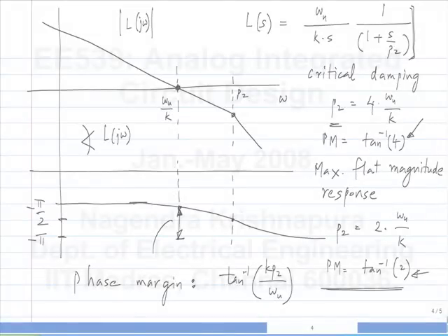Yeah, see, for a second order system, you can clearly define quality factor, you can define phase margin also, so you can clearly do all of this, right? So first of all, given P2 and omega u, I can find the quality factor. So instead of using P2 and omega u, I can use omega u and the quality factor, for instance.